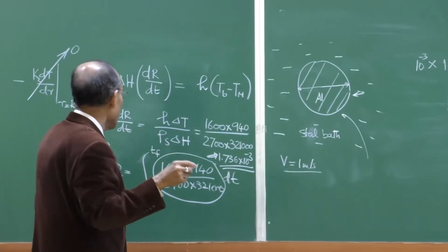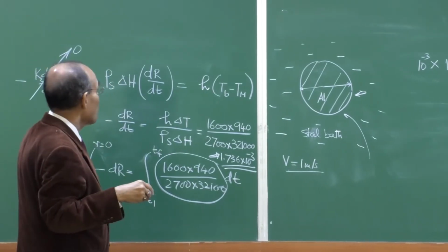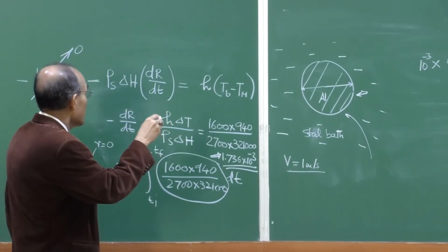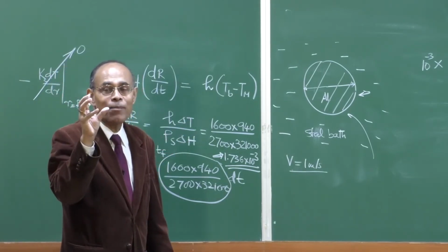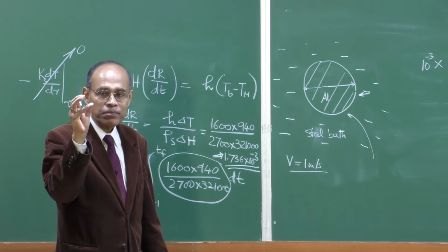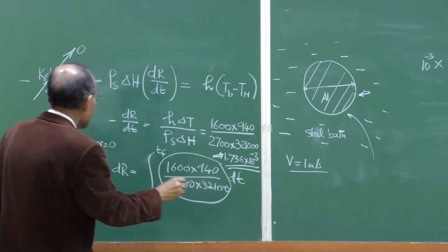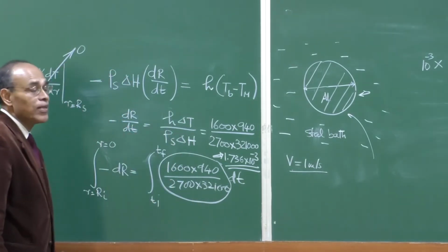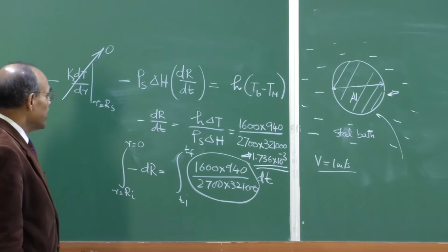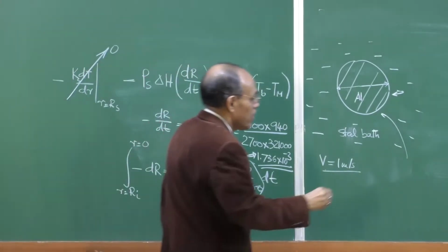mention, and which is discussed particularly in transport phenomena courses, that this is an unsteady process; during the melting period, the radius of the sphere actually decreases. So, a constant value of heat transfer coefficient may not be applicable in this particular case, because the radius itself, what is the Nusselt number based on diameter.